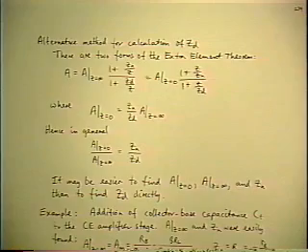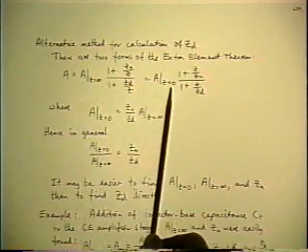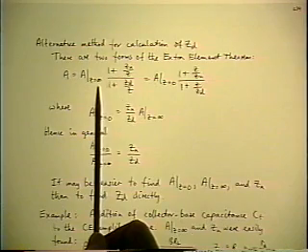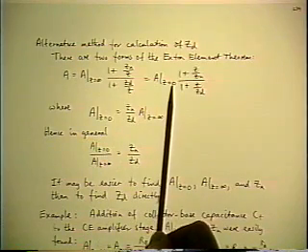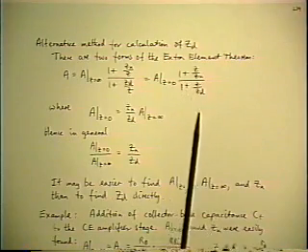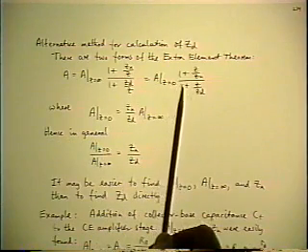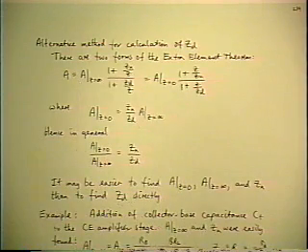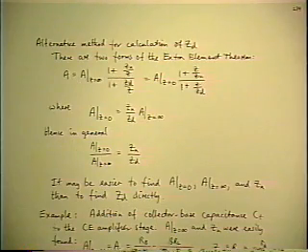There are two forms of the extra element theorem, depending on whether the reference gain that you're starting with corresponds to the element being infinite or the element being zero. They're dual forms. And we found the second version, that for the series element, was obtainable in a couple of lines of algebra from the first one. In fact, this is how we did it.